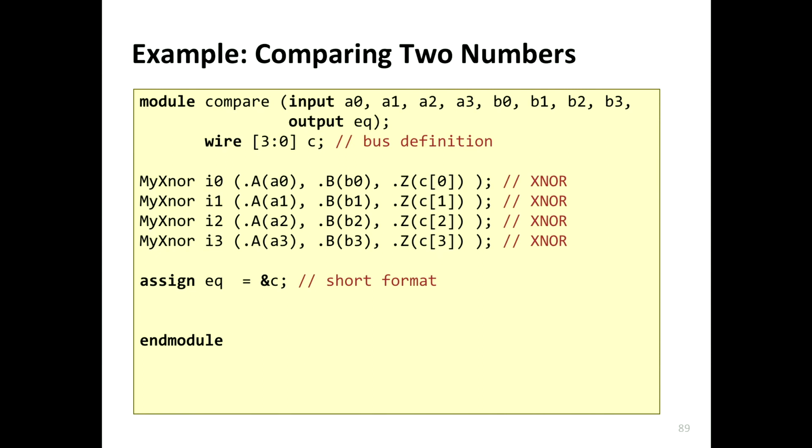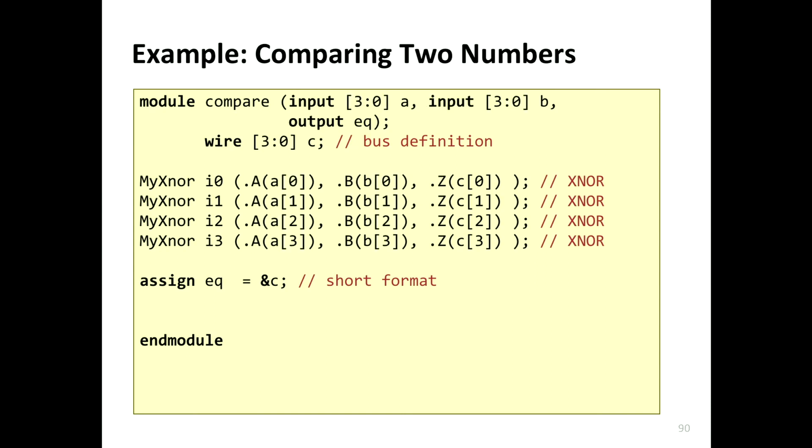Of course, this affects readability, but it's just a way of showing how many different ways you can write Verilog code. And this is not the end of it. I can replace the A0, A1, A2, A3 with a bus, as he mentioned, with [3:0] and [3:0]. So both of them are 4-bit buses, and directly you can include them in your instantiations.